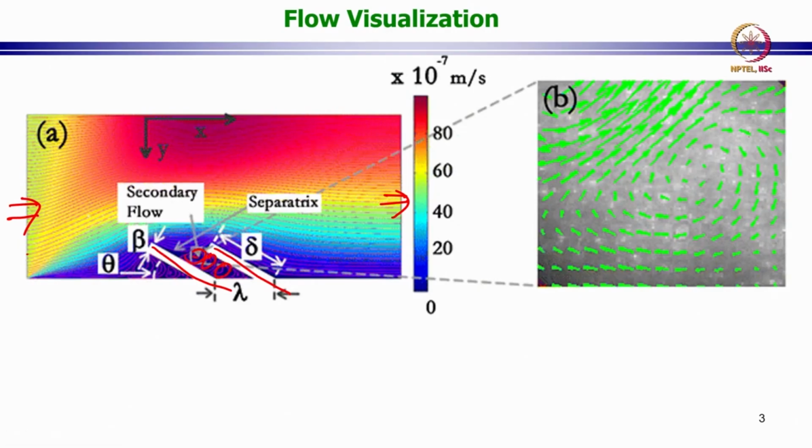And when you analyze the data through particle image velocimetry techniques, you get this kind of a vector field, which actually shows you that there exists a vortex, right? So this is the Eulerian vector field of the fluid flow, and you can see this type of flow that is there. So you can use your experiments to validate any numerical simulations.